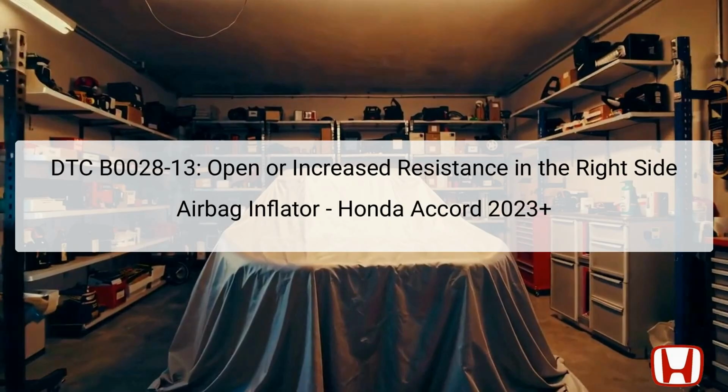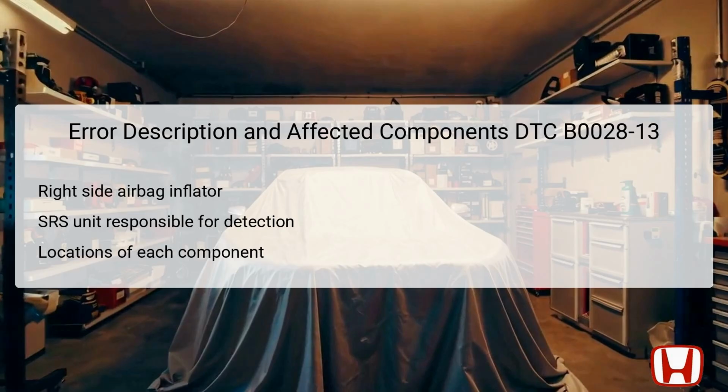This essential preliminary step ensures that all necessary parts have been replaced correctly and that the installation adheres to OEM specifications. The DTC B0028-13 primarily concerns the right side airbag inflator, which is a crucial component of the vehicle's safety system. This inflator is located on the front passenger side, and when it detects a collision, it rapidly deploys the airbag to protect the occupant.